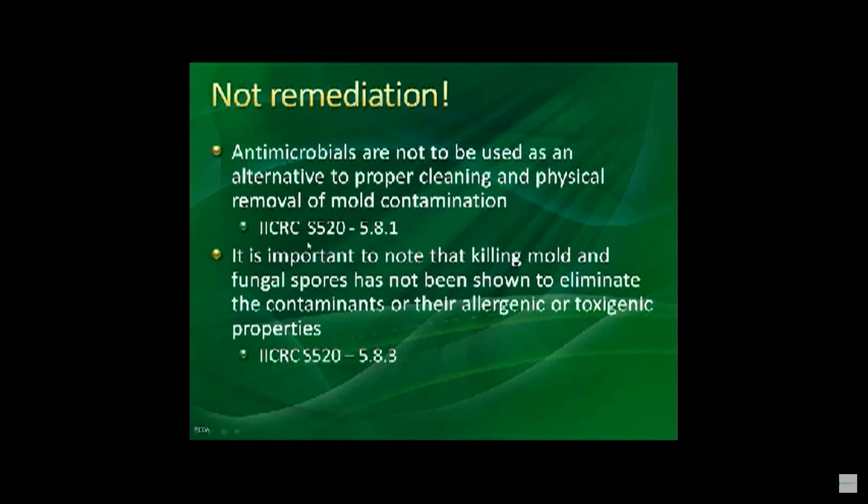IICRC S520 5.8.1 will specifically state that. And antimicrobials that are used to kill mold, where you do not remove it, do not kill its allergenic or toxigenic properties. And again, that is a quote out of IICRC S520 5.8.3.